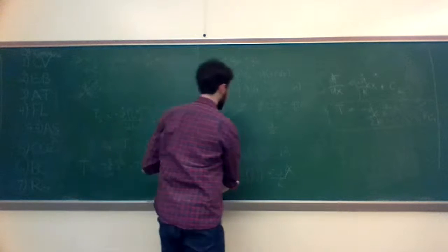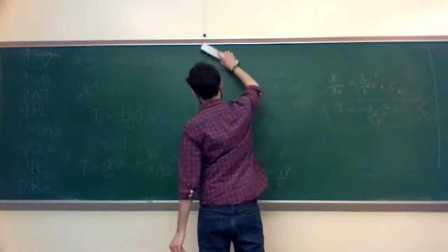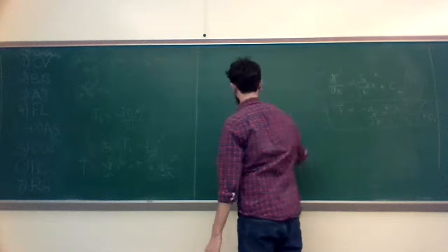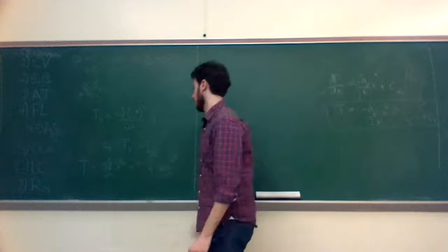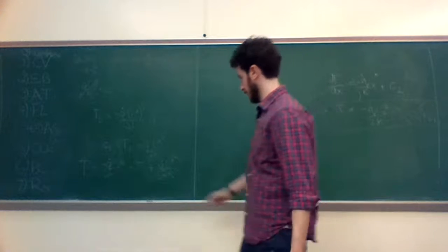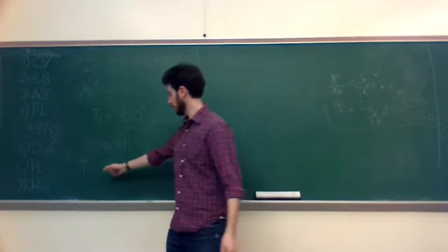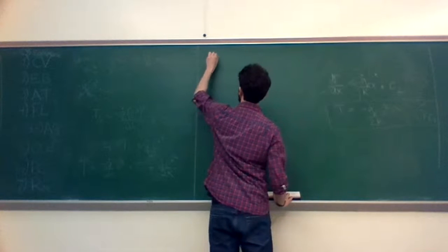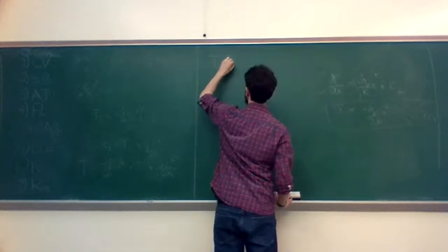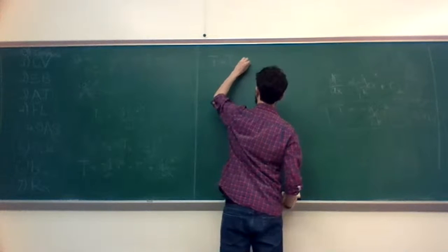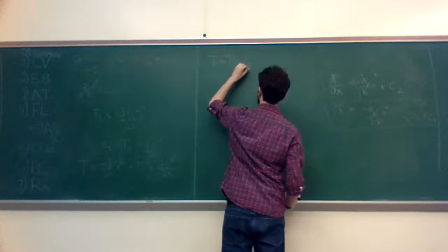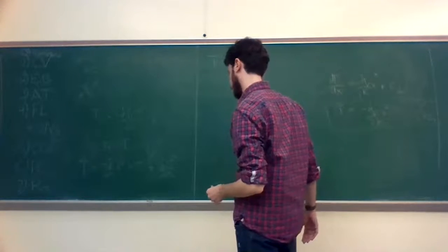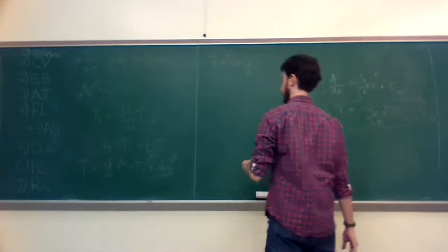And I'm going to erase this part now. And we can just bring these terms together, right? The way to do that is we basically realize you've got q dot over 2k, q dot over 2k. The only difference is L squared and x squared. So we can just write T equals TS plus q dot over 2k times L star squared minus x squared.